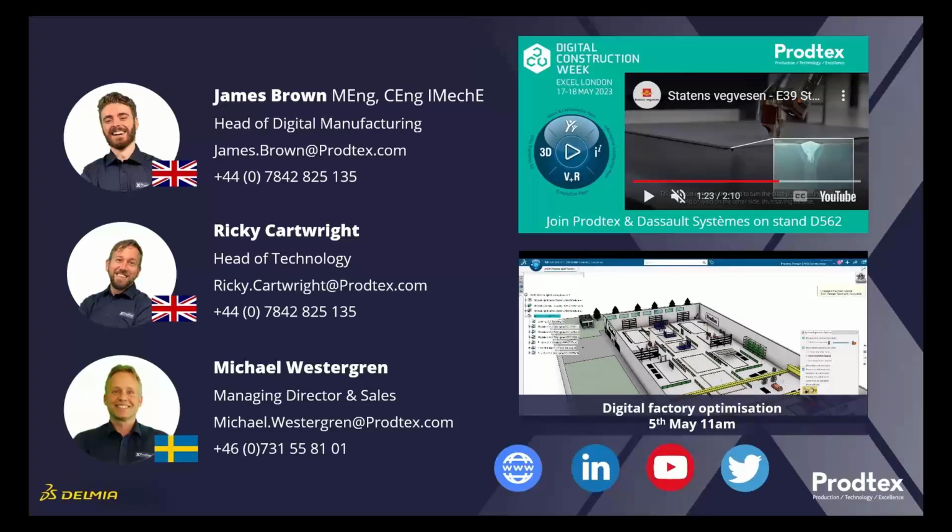I can start. Generally, you will import the point clouds to start with, and you'll tidy them up, because there's a lot of data in there that maybe is not wanted or is a little bit ambiguous, as it's picking up stuff in the air. I personally haven't seen many performance issues with point clouds. It's easily hidden and turned on. If you know your boundary area, you can use a point cloud to create a 3D representation, work with that, and then when you really need to go into the detail, you can switch the point cloud back on. I think you've worked with a larger point cloud, James.